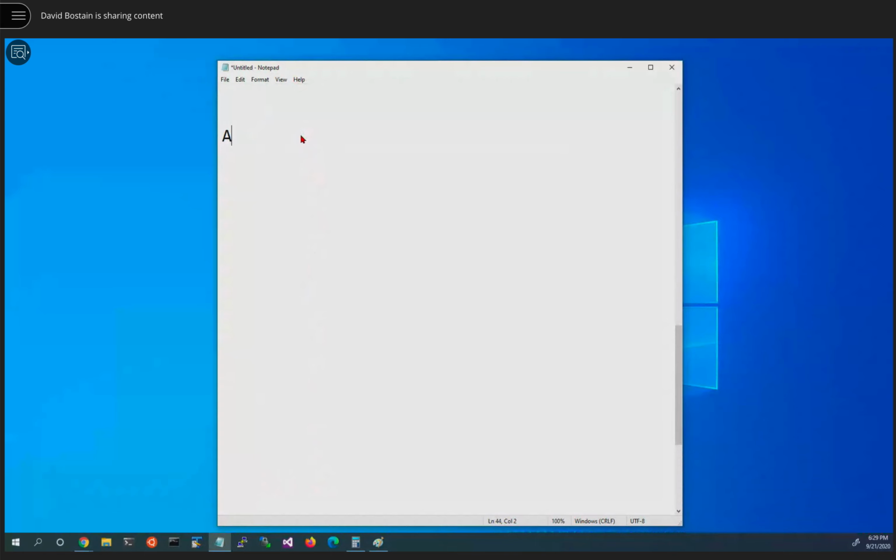What about is there a 1 input one? Can I just have an input? Well, let's see how many lines should be in this truth table? Well, lines were 2 raised to the number of inputs. Okay, so it'll be 2 raised to the first, or 2 lines will be in this truth table. Okay, so the first line is going to be a 0. Second line is going to be a 1. Well, it seems like we'd run out of things to do there really quickly. How many possible truth tables can we write? Well, that's 2 raised to the number of rows.